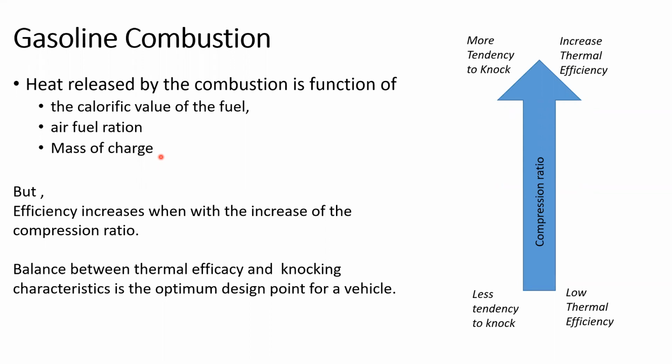That's why for most new modern vehicles, if the manufacturer asks, you have to put in 95 octane petrol. That octane is the combustion or knock rating. So 95 does not mean you have 95% octane in there. It's just a measurement used for knock rating, with respect to something called octane value. Octane is actually a chemical, and it's measured relative to the octane. There's a big process related to that, and I'm not going to go through it.